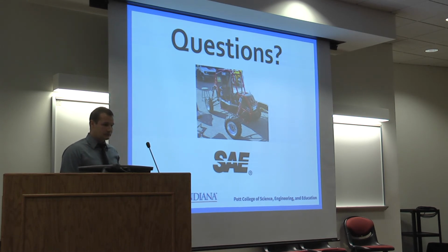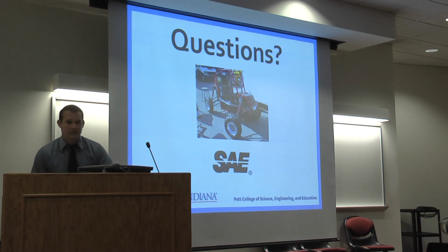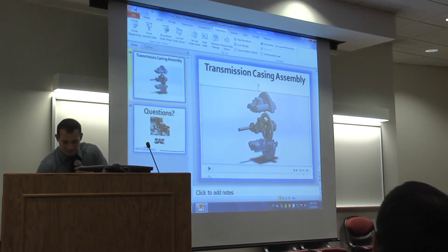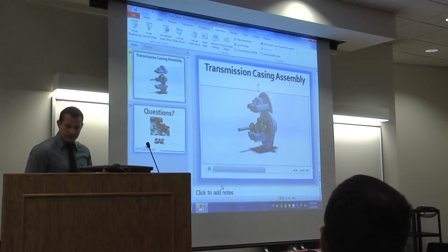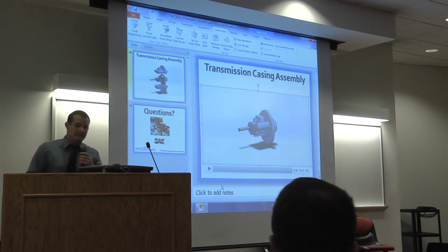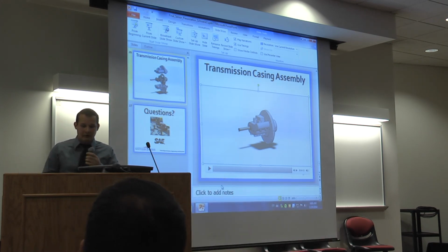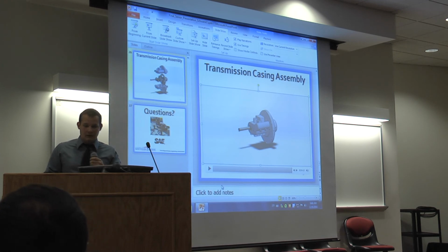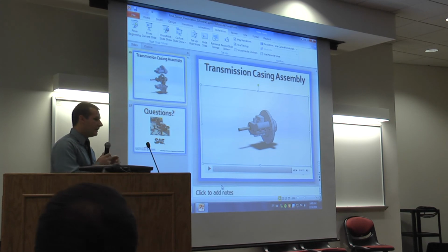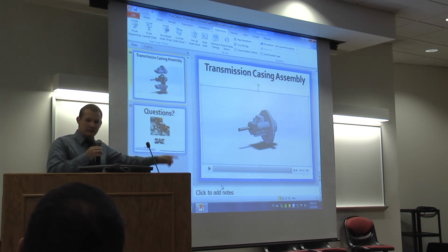Any other questions? Okay, Nick, you had an animation at the end of the whole assembly going together. Is that how you intend to assemble the case? Yes. Let me play it for you again. I wanted to make it into 4 separate pieces because the hardest part was mounting the stationary ring gear in the center. It would be very difficult with having just an upper and a lower portion to install the stationary ring gear. A possible casing redesign could be incorporating the ring gear in the actual casing itself.